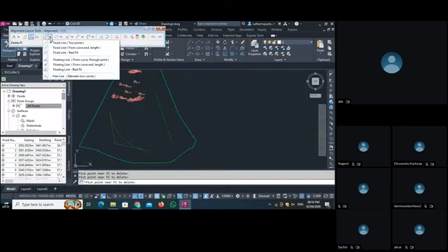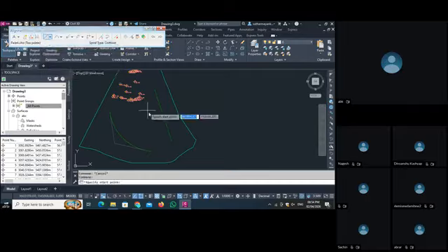Then the other thing you have to know about this line is that there are multiple options here. You can use a fixed line. If you want to connect two points, you can choose this fixed line. If I select here and select the two points, I can get one alignment here. See, I am working on all of this in alignment number one.